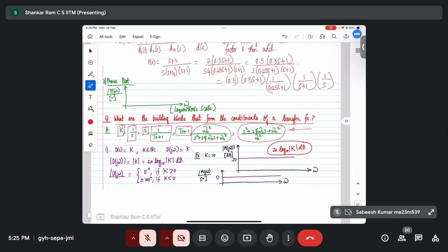We do a sine sweep test, and we look at the Bode plot. It so happens that by and large, the lower order model that people will construct for a plant transfer function, even in automotive applications, will contain these terms: the integral term, the derivative term, the first order terms, and the second order terms.